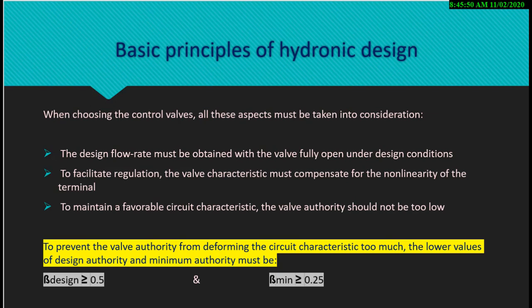Last, to maintain a favorable circuit characteristic, the valve authority should not be too low. To prevent valve authority from deforming the circuit characteristic too much, the lower values of design authority and minimum authority must be respected. The design authority should not be less than 0.5, and the minimum authority should not be less than 0.25.